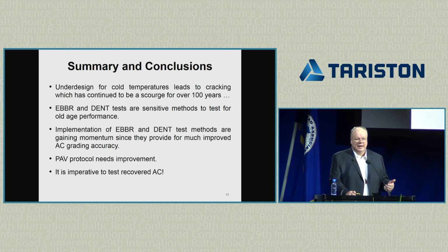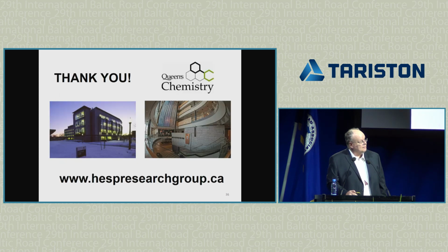So take loose mix samples from the paver, recover, extract the asphalt cement, and test that. You can save a lot of money as an agency.